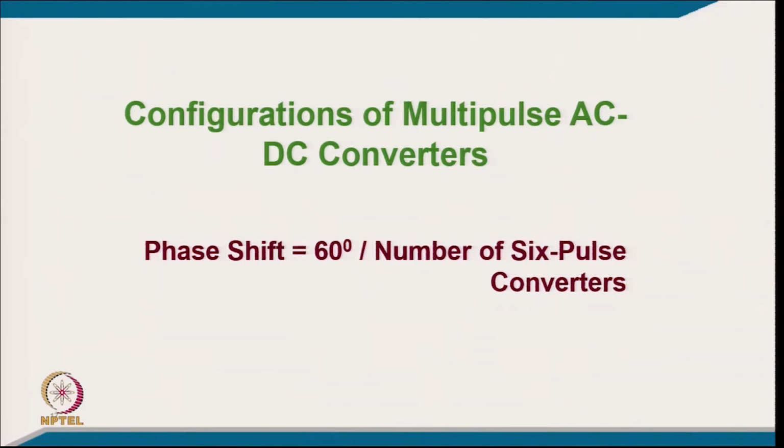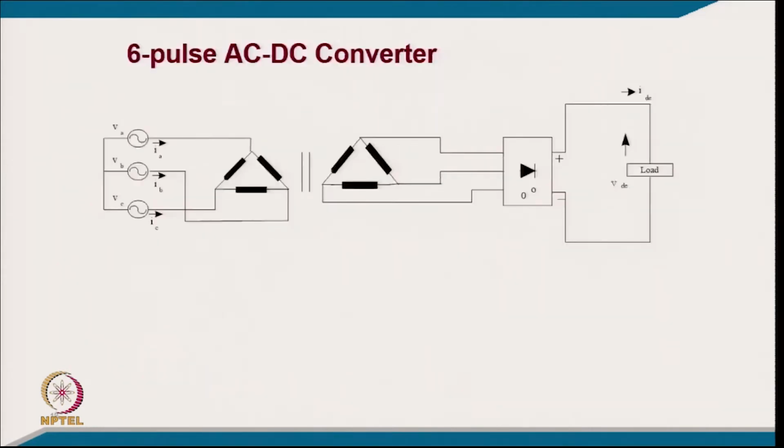So, like that, of course, a large number of pulses are also used. Typically, if we talk about Navy examples, a minimum of a 36 pulse converter is required, because they can't afford more than 3% THD on the input AC mains current. So, the number of converters also needs to be reasonably large. So, that is the one concept of phase shift. There are 3 concepts used in this: one we use phase shift, another multi-phase, and third pulse multiplication.